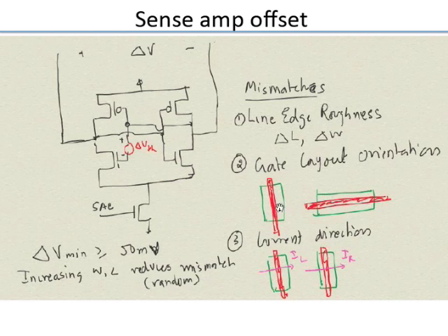So similarly here, that is why these are called systematic variations, where you can account for these variations if you can study all the factors which go in and determine that. So these deterministic or systematic variations can be controlled or overcome by doing specific things either in the design or in the process, and that is done a lot of times. Whereas for the random ones, you just have to do averaging. That's the only way to deal with these random variations.